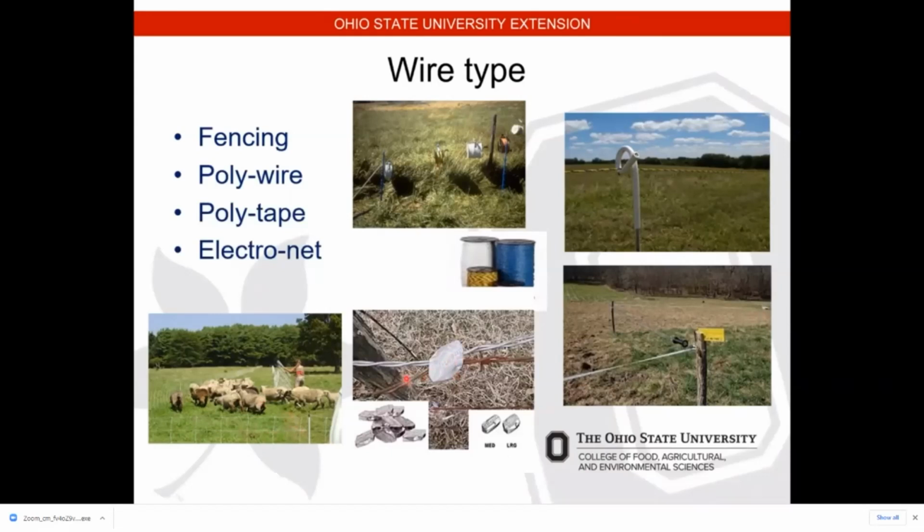Barbed wire, you don't want to electrify barbed wire, because every time that electric comes to one of those barbs, it won't short it out, but it just kind of takes some of the juice out of it. It's kind of like imagining water flowing through a line, and then it comes to dead ends every so often. It just won't flow real good. The gripples, I'll talk about them later, but there are 2 different sizes of those. I've used them. They got some good points and some bad points, but we'll get to that in a minute.